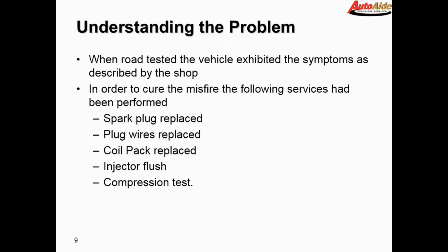Well, when we road tested the vehicle, it exhibited the symptoms as described by the shop. So, they're dead on in their observations. In order to cure the misfire, they had done some work on it. Spark plugs, plug wires, coil pack. This was a V6 with waste spark. They did an injector flush and a compression test.